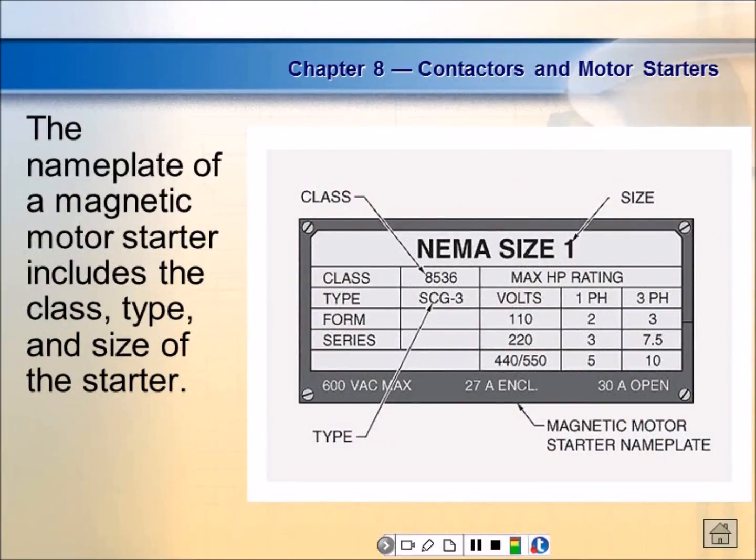If it's rated at multiple voltages, it's going to tell us the two voltages that it's rated at, and in industry you'll run into a lot of dual voltage motors. And of course, the only reason you would wire this low voltage is if high voltage is not available. If high voltage is available, then you're going to run the motor on high voltage. You don't understand why. Because why?